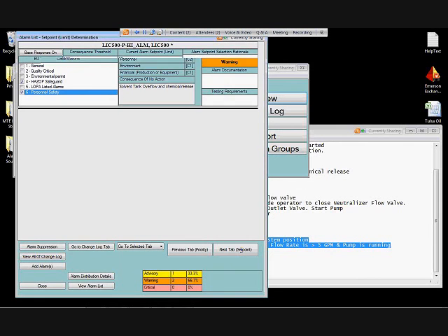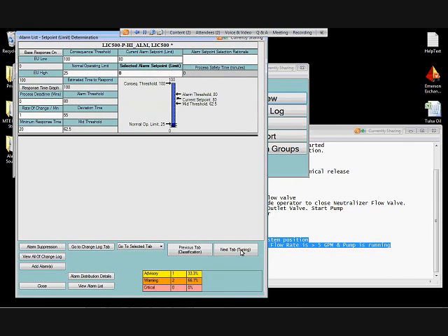Next, we want to look at the alarm limit, and I can see that right now it's set at 80 in the DeltaV system, which I know is probably the default for this control module. Now the tank is ranged 0 to 100, so it'll overflow according to these drawings when the tank level reaches 100. So that is the consequence threshold that we need to be concerned with.